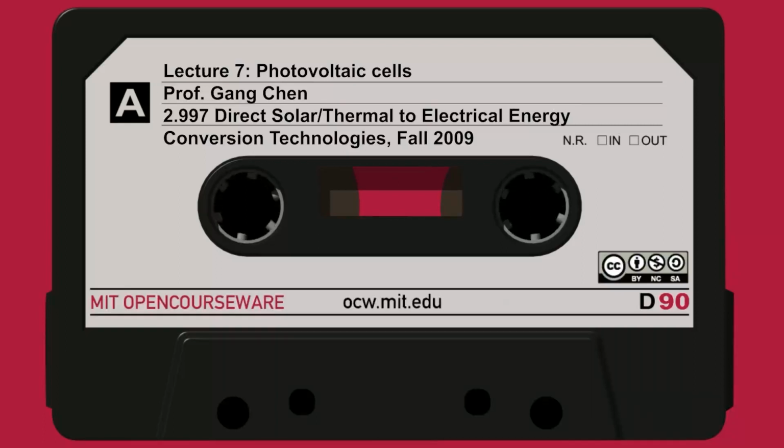So now if light comes in, this is the electron-hole current generated due to absorption of photons. And once I build the voltage, this is the forward current that balances it. When I have voltage, I drive the diode, and this is the electron-hole pair generation, the counter current going this way. And of course in a solar cell, I want this to be less than this. If you understand that, that's the solar cell.